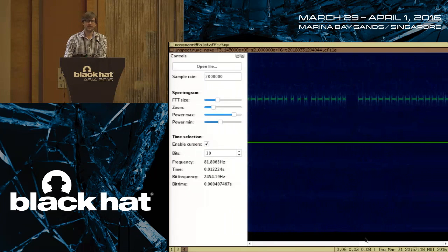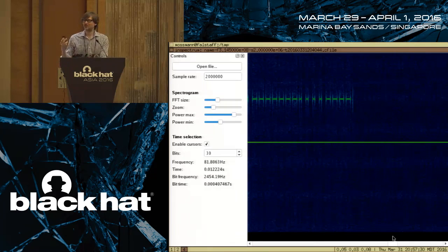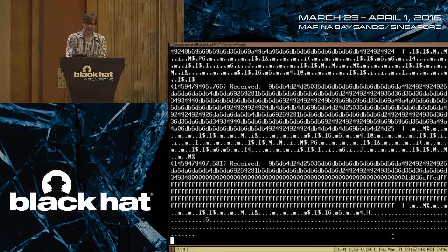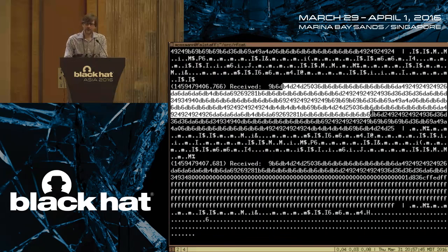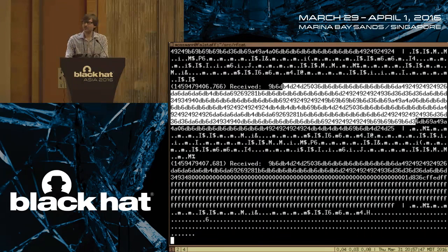And if I were to compare this, I'd probably notice that it's really transmitting the same information over and over again. And that's just a crude way of dealing with unreliable radio communications, right? They could use some sort of sophisticated forward error correction or something, but they don't. They just send the same packet a whole bunch of times in a row and hope for the best. And so that's a cheap and easy way to improve the reliability of a radio system. So it's not surprising that we see a lot of repetition here.